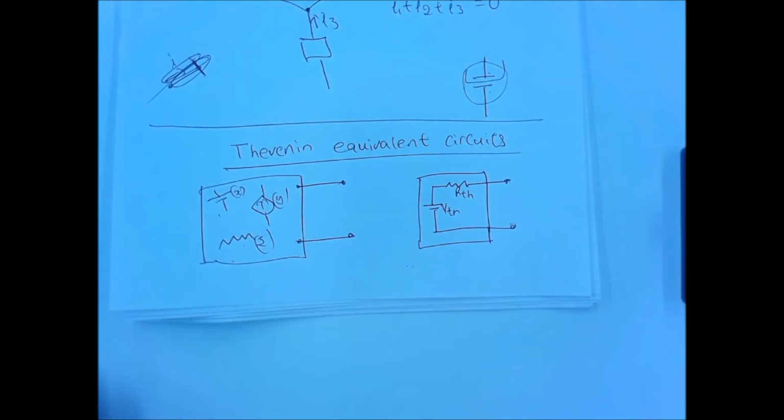For the Thevenin resistance, you add every resistance in series or parallel. But you don't know how they're connected. Don't you short circuit all the sources? Yeah, you go into the box and switch off all the power supplies. Switching off the power supplies most often means shorting them. If there are current sources, you open them. That's how you switch off a current source: you open circuit. So go into the box, switch off all the batteries, or if there are current sources, disconnect them.